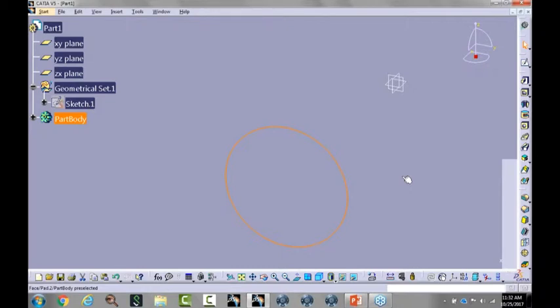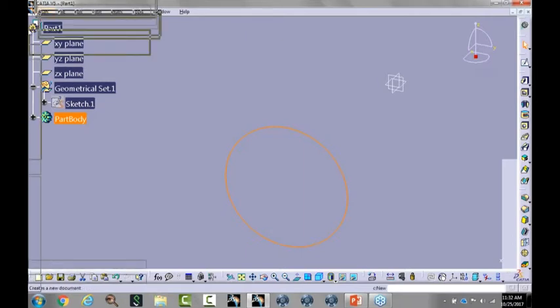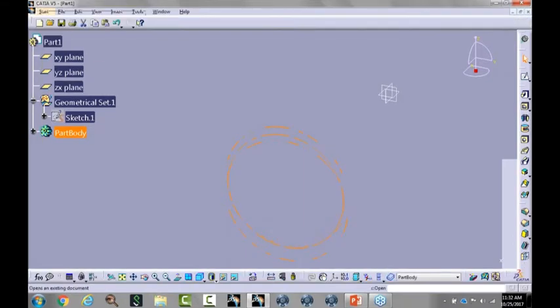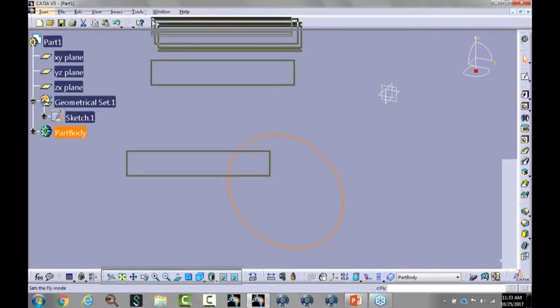So the recommendation that I always give, I'm also a CATIA instructor. I wear a whole bunch of different hats. Let's not worry about all of them. But one of the recommendations that I give is when you are given a new CATIA workstation that's vanilla settings, go in and make all the changes the way you want them and then exit out of the product. So for example, I always recommend that the standard toolbar that you drag up here to the top and start a new toolbar area, and the same for the view.